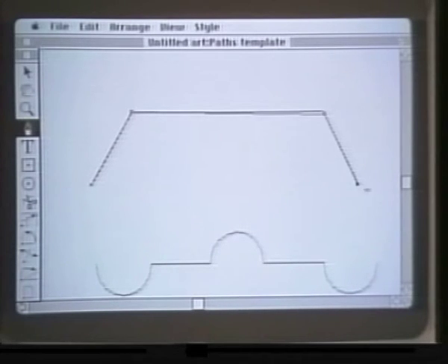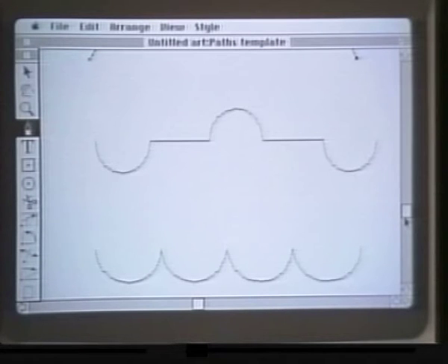I'm going to finish off this and then hit backspace twice to get rid of this curve so that I can redo it. I'm going back to the Pen tool. Now when I click, I will hold down the Shift key on this section to make sure that the line is horizontal. The Shift key constrains to horizontal and vertical and 45-degree angle lines. This is a very useful tool. The next set, we have a curved section followed by a horizontal straight section followed by curved sections, etc.